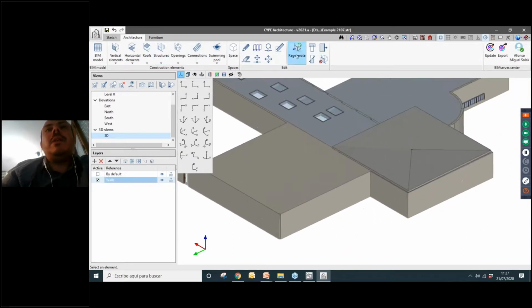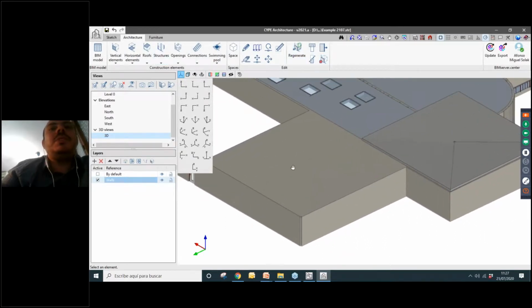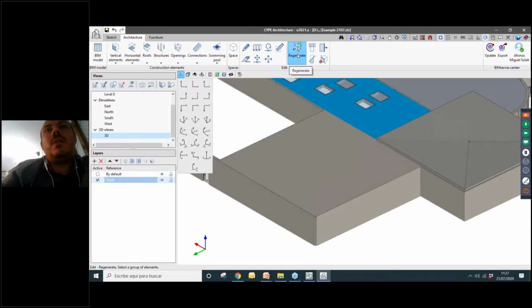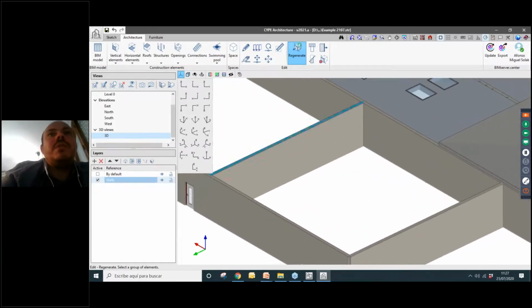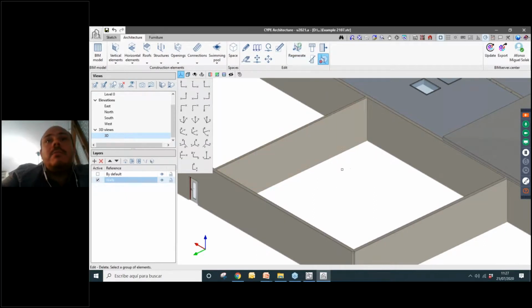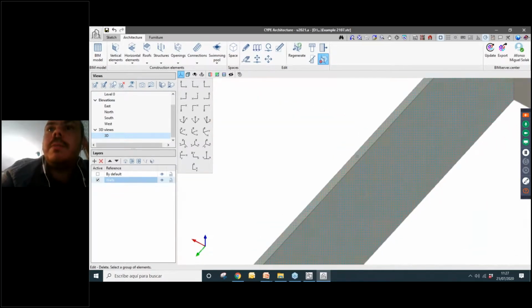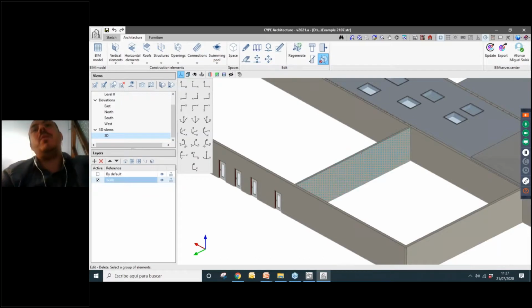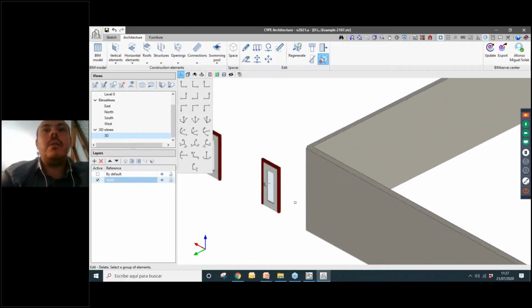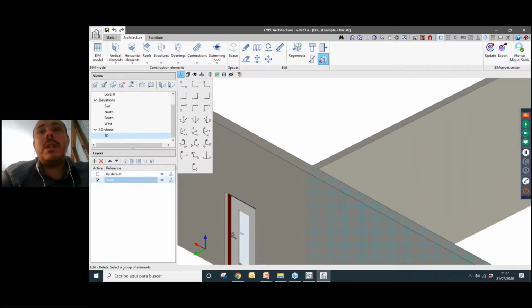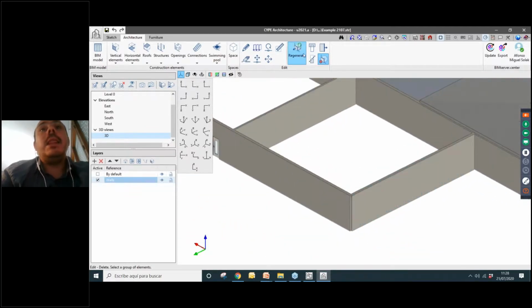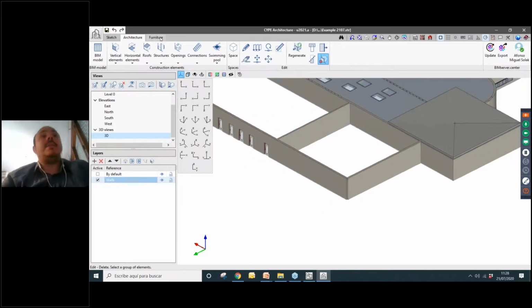Okay, if at any moment I would like to regenerate, to revert the situation, I just use this tool here, regenerate, and click on that object, and we will return to the original position. Okay, here we can delete one surface of the building. Okay, watch out, it's just one surface of this wall, not all the building, except when we select all of them, for example here. Okay, but we can select one surface and delete just one surface. Okay, and here we can divide, cut by plane, and subtract elements between them. Okay, so quite nice.